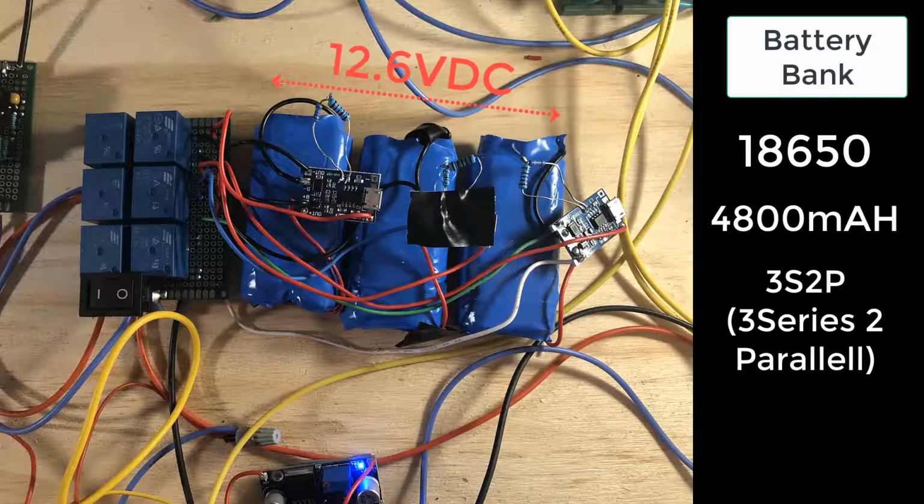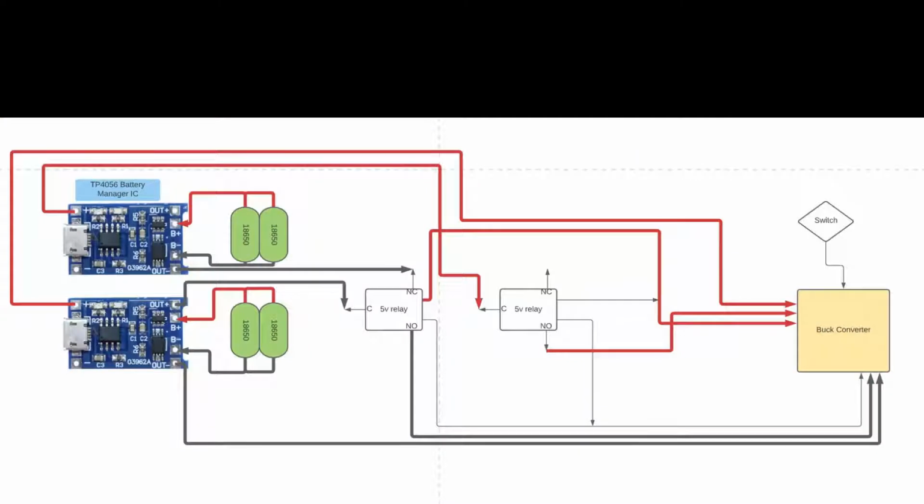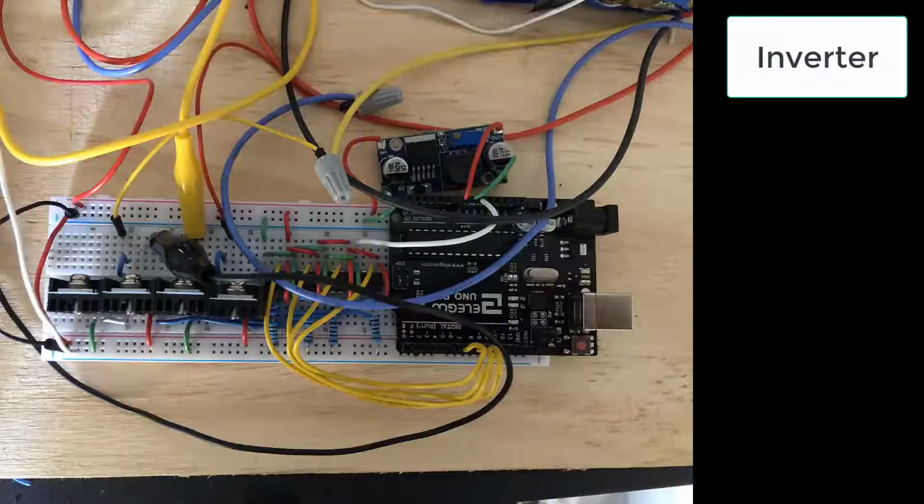We have a 3S 2P setup. This supplies 12.6 volts to the inverter. The controller PCB we are using is a TP4056, which was redesigned to lower the current draw for each cell to prevent an overcurrent on the buck converter supply. We also had to design a charging circuit implementing relays to balance charge each cell individually. I will mention that one downside of this design is that we cannot supply power to the residential load while in charging mode. Now we look at the inverter.